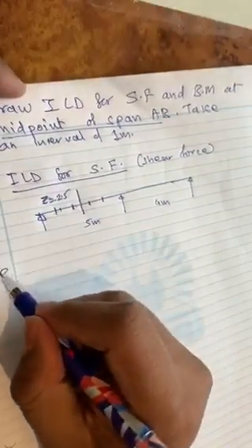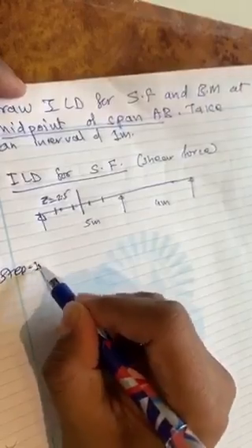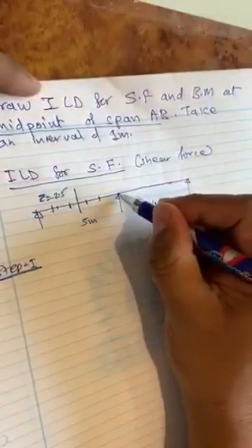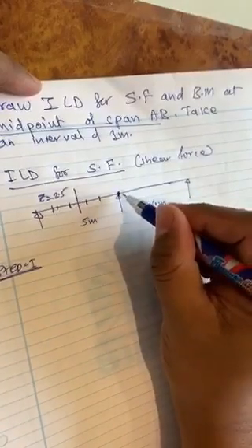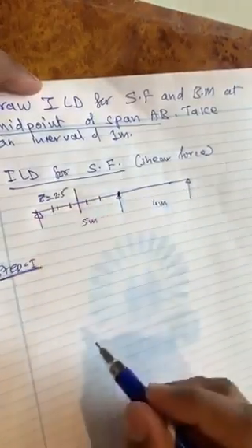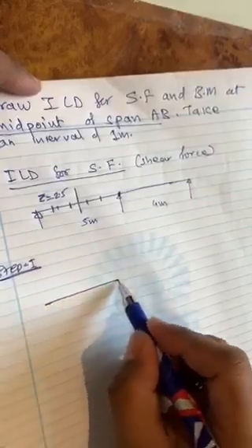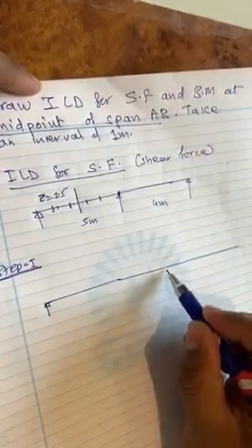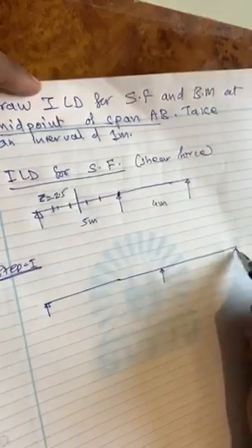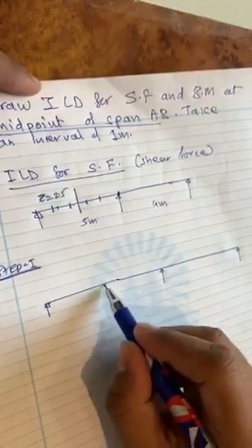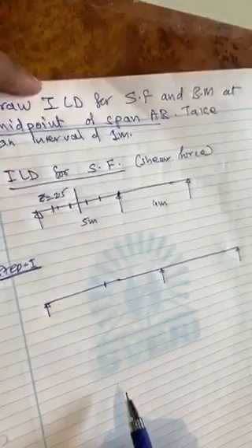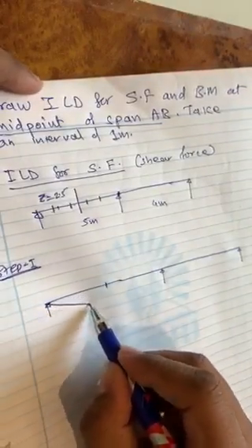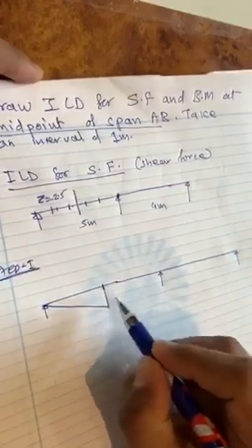So we will go step by step. As you know, the first step is to find the ILD of the determinate beam. So how will you make it determinate? By providing a hinge here, this beam becomes a determinate beam. Let me take it a little bigger so that you can see it clearly. So again we have to break it at 2.5, that is half. Okay, so then you can see the ILD will come something like this,